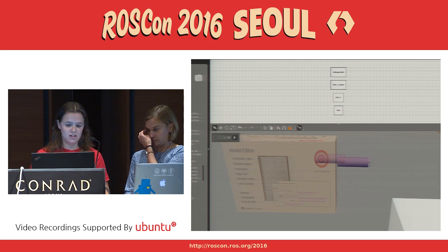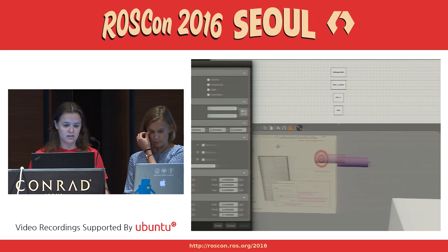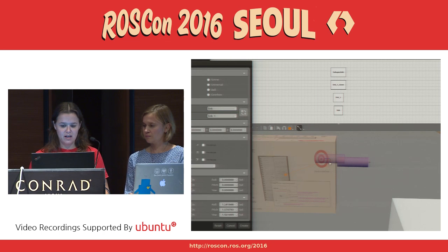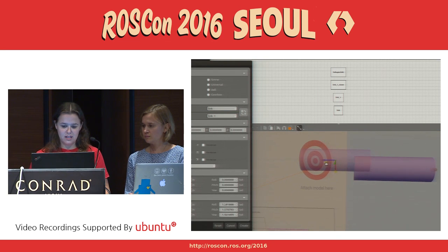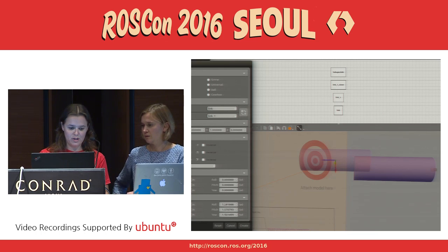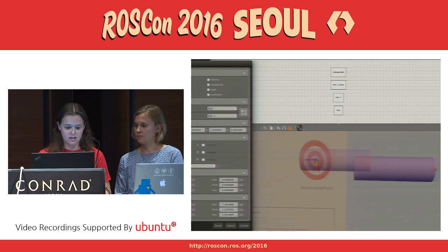Let's make some joints. So there's the joint creation tool here. You can click on the parent link and then the child link, and we create a joint. Then we can see the axis is not where we want. We want it to be green, which is Y. So we just choose it here, and we can quickly move it here on the Z up, which is the blue one. And let's move it a little bit more up. Yeah, that's good enough for now.